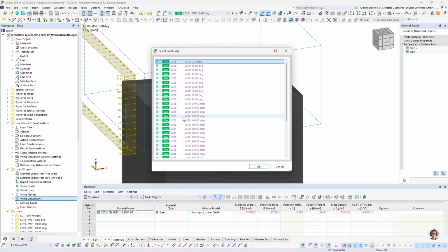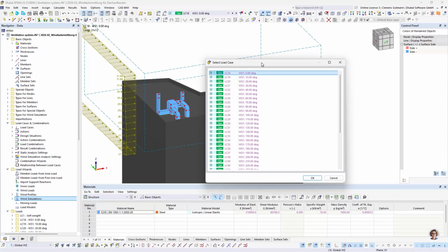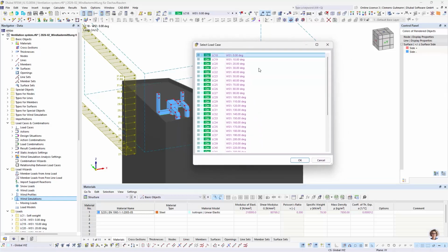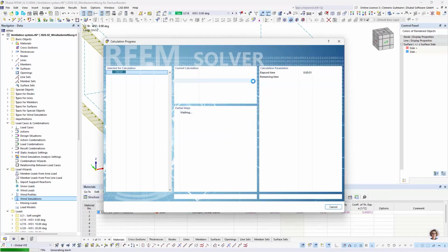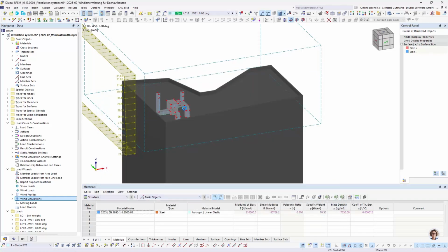For one analysis, you have one wind tunnel with a specific size, and one model file that is rotated at the specified angle, and this cannot be done in the same file with RWind 3. So here you select the rotation of the model, and then the geometry is exported and made ready for the transfer.